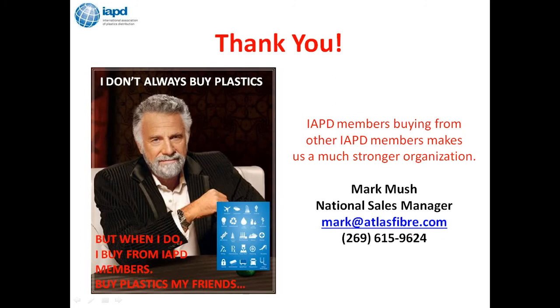Okay. Going back to one of our previous questions that was asked, I think she wants just a little bit more clarification for what's the difference between G10 and FR4. What does non-brominated mean? Well, or if we could have a little bit more clarification to it. Sure. As Mark explained, the FR in FR4 means flame retardant. In order to become flame retardant, there is a chemical called bromine added to the mix. The pure G10, as opposed to the FR4, does not have any bromine in it. So we call it non-brominated.